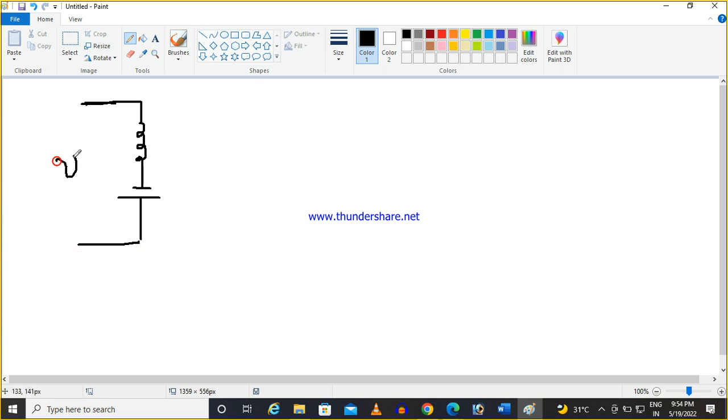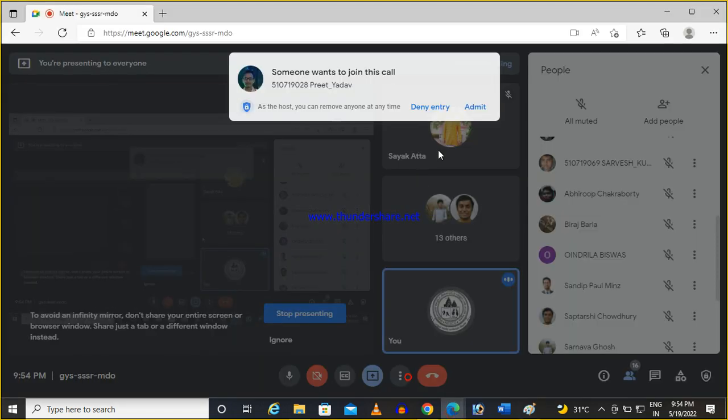This is the Laplace transform of the source voltage in the S domain, and this is Ls, where S is the Laplace operator. You know, S is equal to j omega. This voltage is L I0 plus, basically the initial current which was flowing through it.